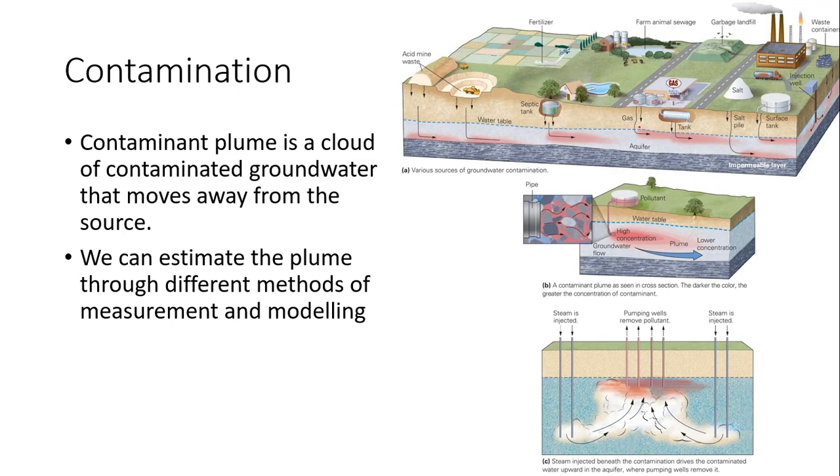And so if these are entering our water table, we'd be able to look at the direction of flow based on other wells. We would be able to drill some of these wells and measure the parts per million contaminant of this specific soluble chemical or whatever it is. You'd be able to test the water for those things, and you'd be able to look at the different concentrations and figure out which way the flow is moving.